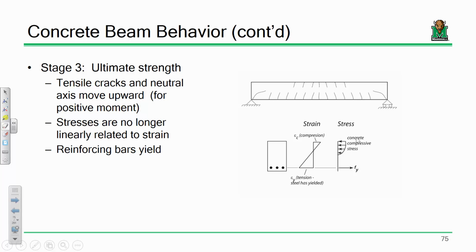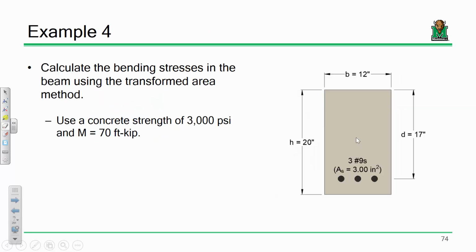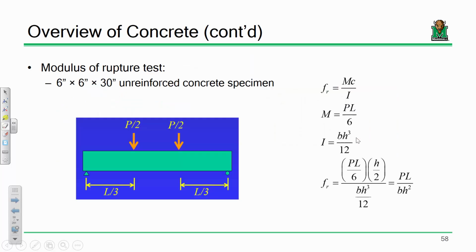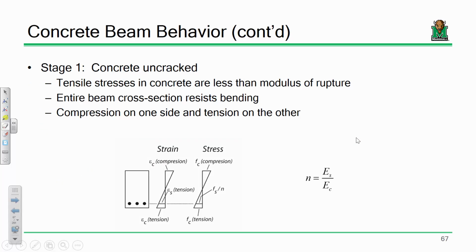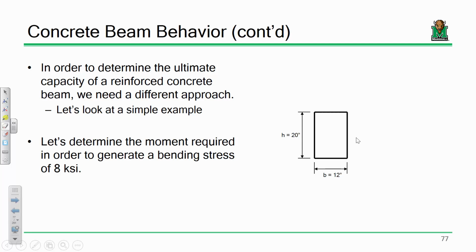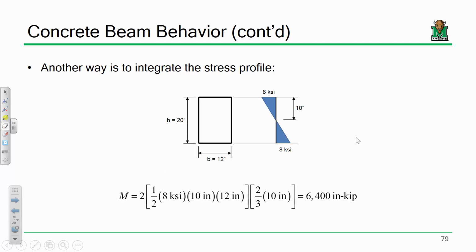In other words, what is the absolute maximum load that a reinforced concrete beam can take before it is gone? Okay, now, that is actually not that easy to address when you consider the following. These are stress-strain curves for regular concrete. They are very non-linear, right? Remember your bending stress profile for beams? Remember how it looks something like this?